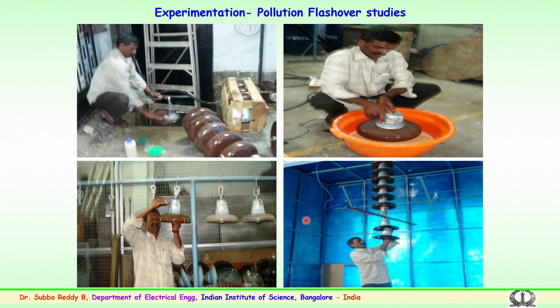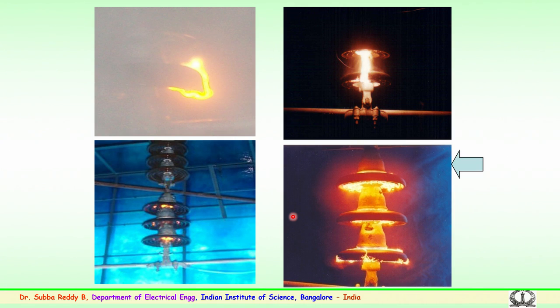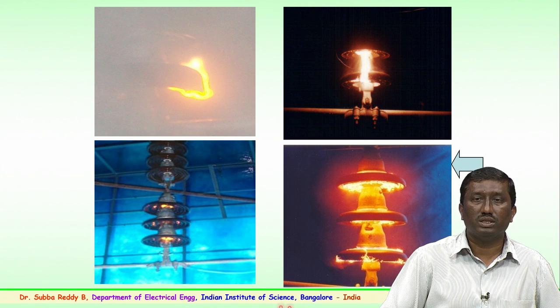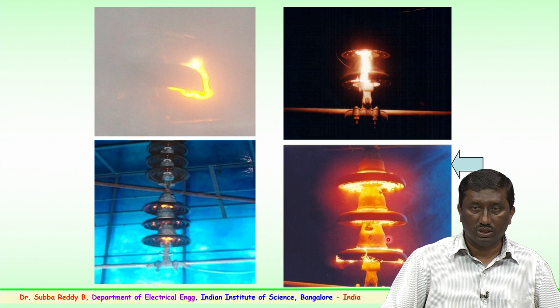Verification of the insulator flashover performance for a normal string, and also the strings with the field reduction electrodes, has been carried out and successfully demonstrated for strings consisting of a single disc to 3 discs.